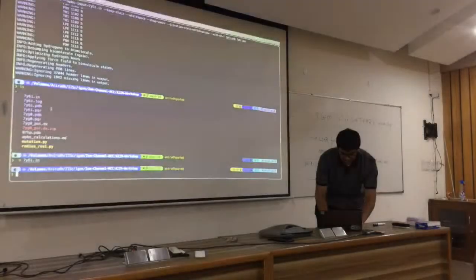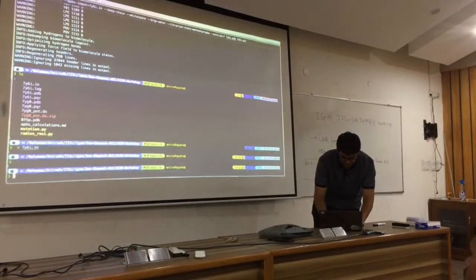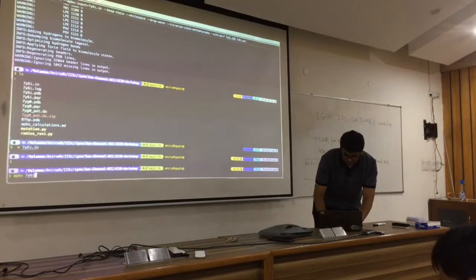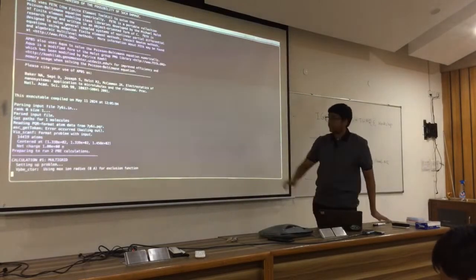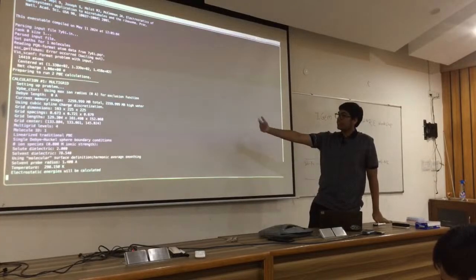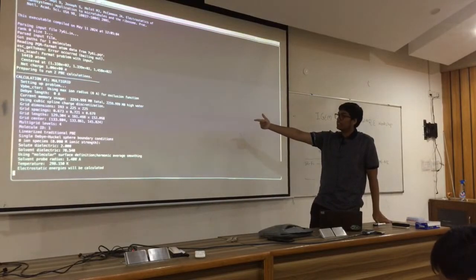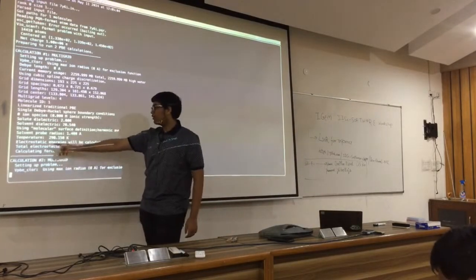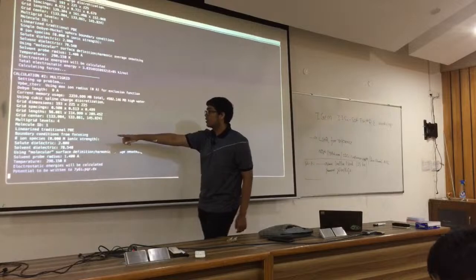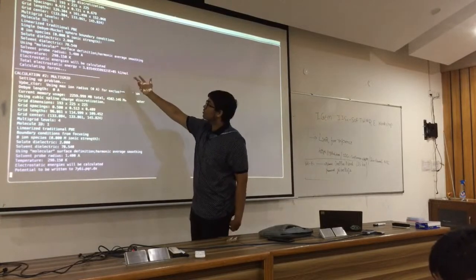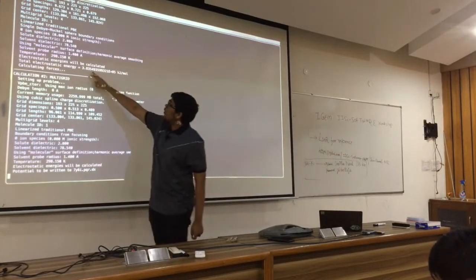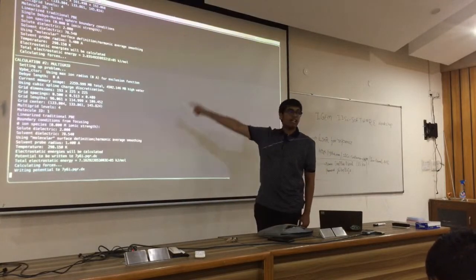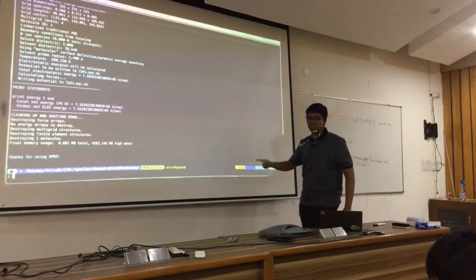APBS calculations can be done very easily. Just do write APBS. We generated the input file, the 7y6i.in. This will do all the calculations with different iterations, and you can see what all values it takes: solute dielectrics, solvent dielectrics, temperatures, what other electrostatic energy is also written here, the total energy. So these values are also very important, so don't skip this.